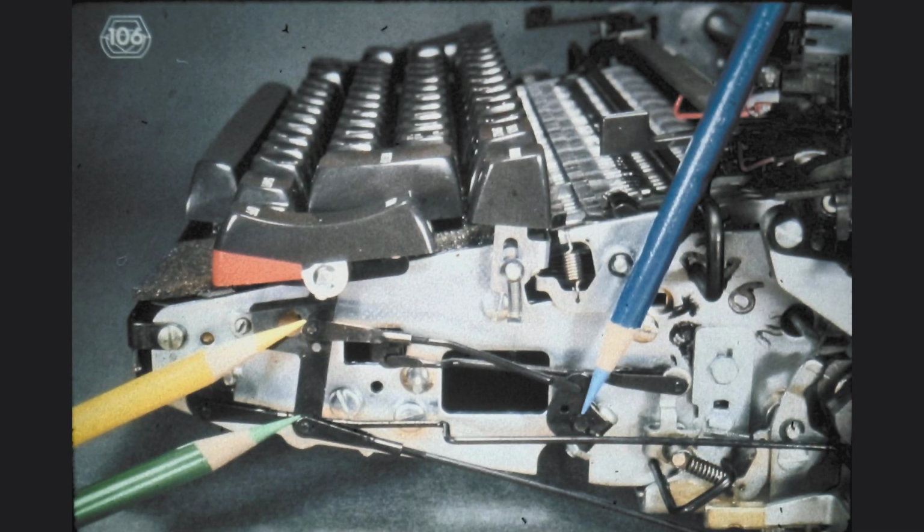For the off position of the on-off key, we follow the same criteria we used for the rest position of the tab set and clear key. The key top should be aligned with the slope of the keyboard when the switch is in its off position. But here, we have a few additional things to consider. Notice that the clevis connected to the key stem at the point indicated by the green pencil leads to the on-off switch. The yellow pencil connects the key stem to the keyboard lockout bail.